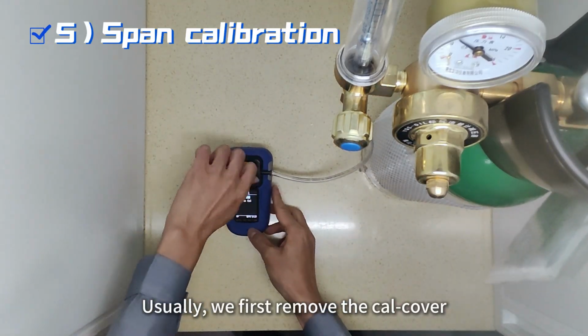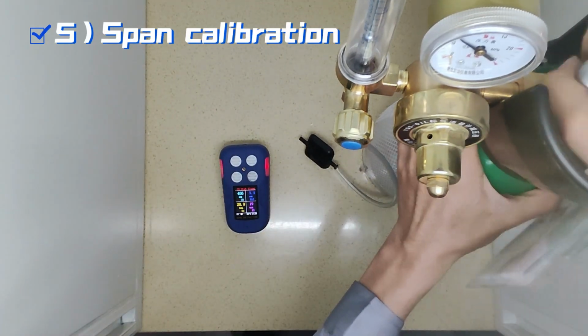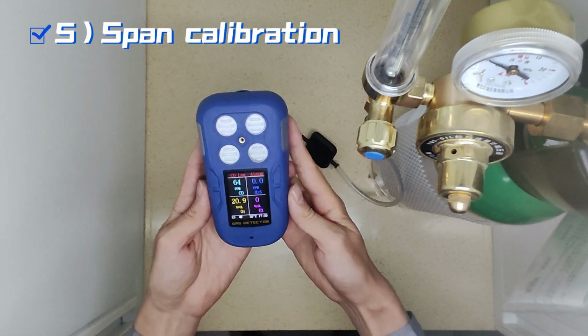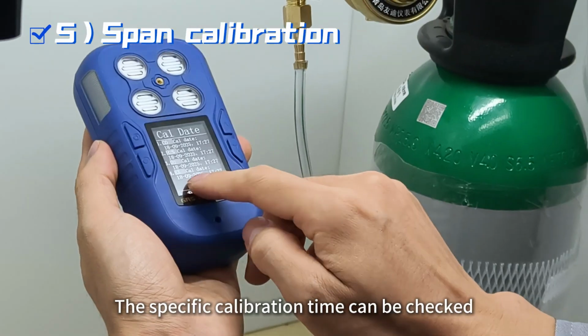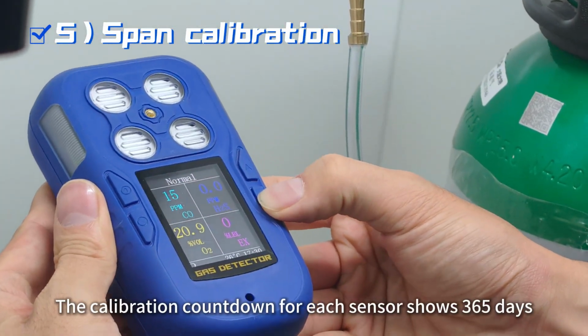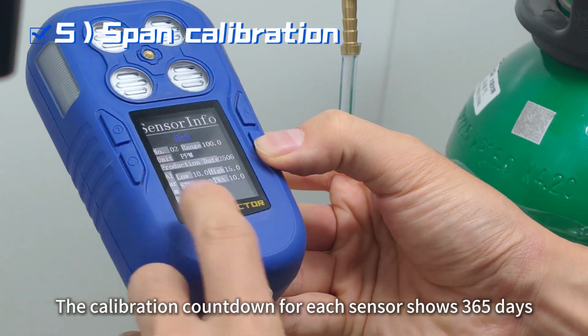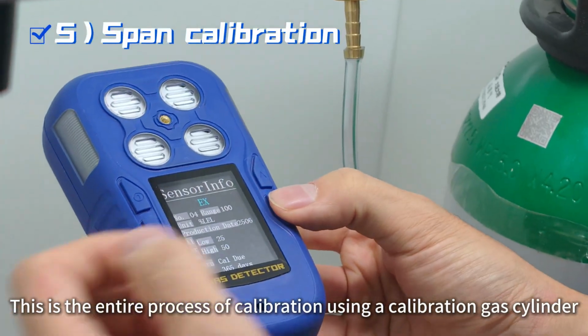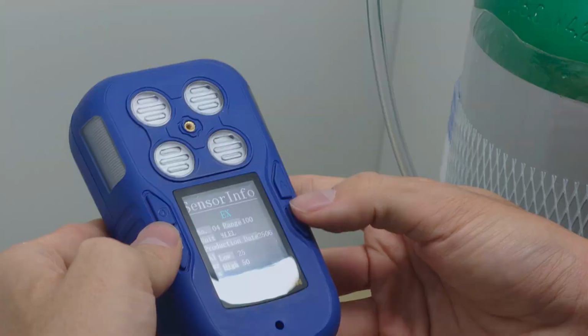Usually, we first remove the cal cover, then close the gas cylinder valve, followed by the flow valve. The specific calibration time can be checked in the menu information function. The calibration countdown for each sensor shows 365 days. This is the entire process of calibration using a calibration gas cylinder.